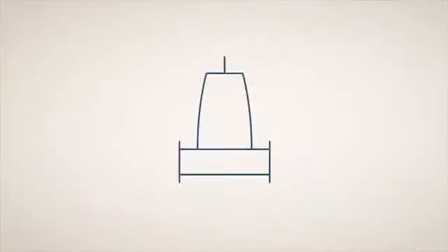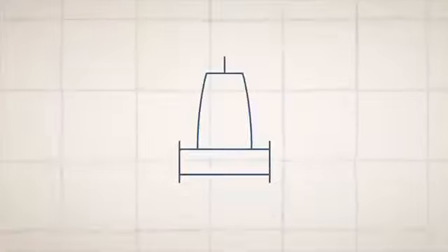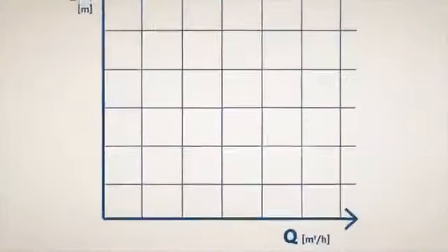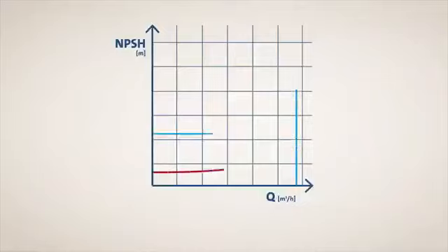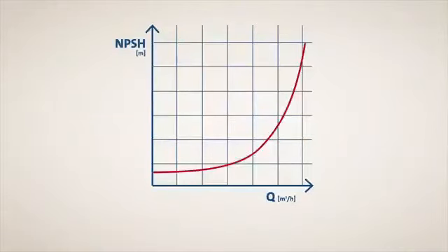Pump design can also affect what the pump performance curve will look like. There are both flat and steep pump curves. Flat curves occur when there is a small change in head, resulting in a big change in flow, as you can see here. Steep curves, on the other hand, occur when there is both a small change in head and in flow, as shown here.